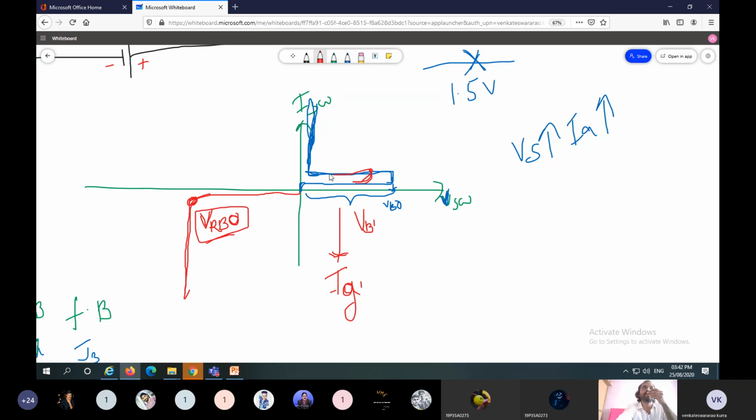So then the direction of current is like this. If we increase the gate current, so it means IZ2. If IZ2 is greater than IZ1, the SCR gets turned on at lower voltages. So with increasing gate signal, at lower supply voltage also we can turn on the device. These are the static characteristics of SCR, and these characteristics do not depend on time.